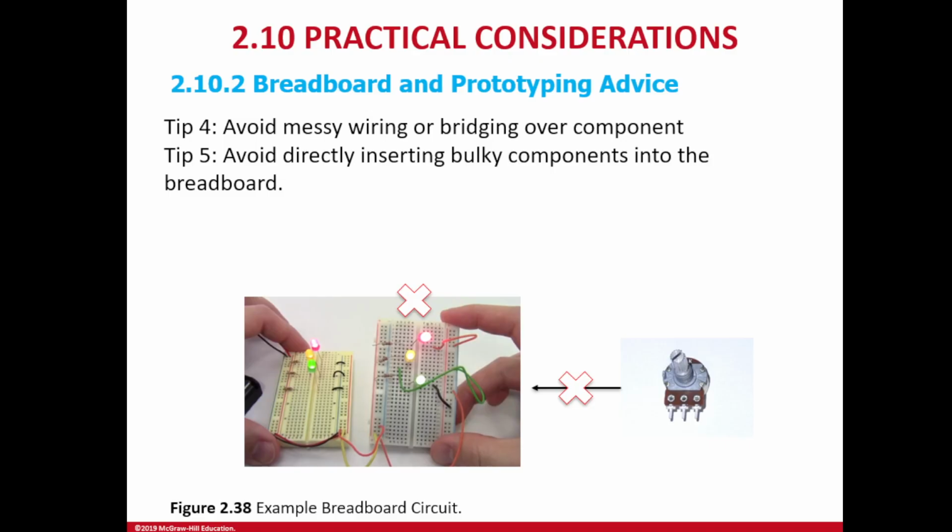So it's better to use some different wire. And after you have finished, you need to pull all the components out, because if you leave components in the breadboard for a long time, the spring will come loose.